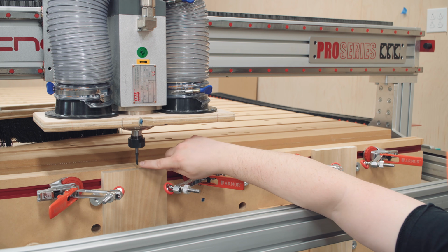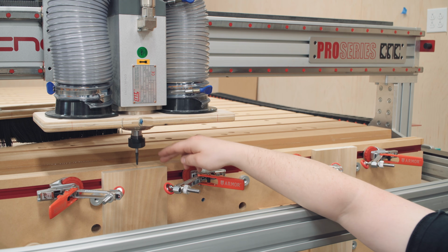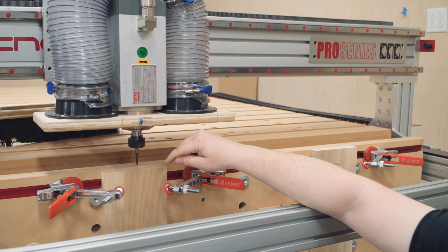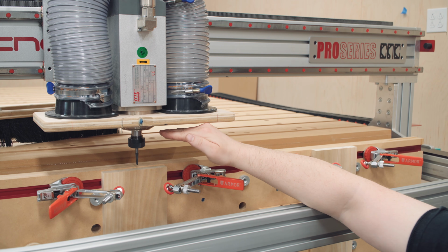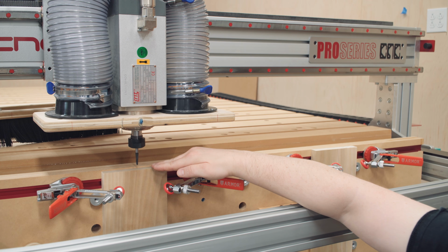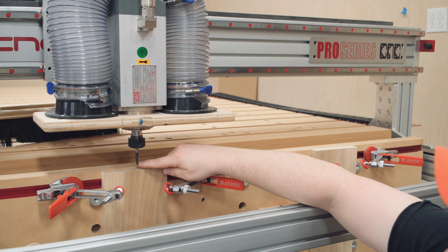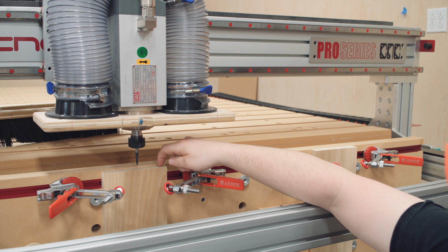This is Z0. I'm making through cuts in this orientation. So let's just say dovetails or box joints. You want the cut depth to be the same value or a smidgen more than the thickness of your material. So let's just, for the ease of this, say that this is 3/4 of an inch material, which it is, and I want to make a perfectly 3/4 cut. So a 3/4 depth of cut, which means I need to raise this bit by 3/4 of an inch so that I have a reference surface for the top of this.